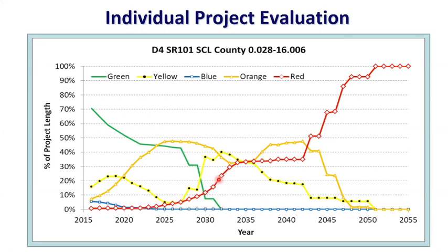Or you have a lot of other options there. You can control the dwindling of your green pavement, right? By doing preventive type of intervention. For example, you can intervene maybe by 2021. You start to do proactive type of treatment so that you bring your green component up, right? See that green is dwindling. You can also jump in to do thin overlay type of treatment. Maybe you fix the yellow, right? Because see here, your yellow already has that much. Probably you want to do something out there to fix up the yellow.